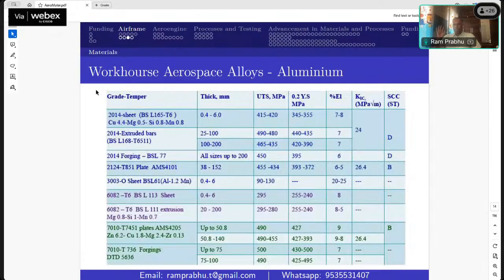Aluminum manganese alloy sheets for the floors are 6082 aluminum magnesium silicon alloy, or 7 series wherever I need a very high strength, 7050 instead of 7075 aluminum zinc alloy. These alloys are prominently used in the airframe structures.